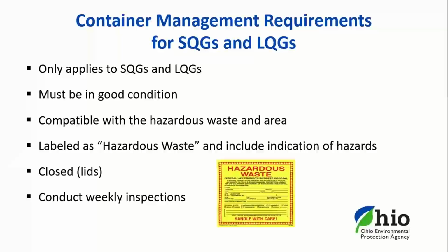The container management requirements only apply to SQGs and LQGs. The containers need to be in good condition, so no signs of dents, bulges, corrosion, or visible leaks. The containers need to be compatible with the waste that's being stored, and they need to be properly labeled with the words hazardous waste and an indication of the hazards. Lids need to be kept closed except for when you're adding or removing waste or temporarily venting the container, and the container areas need to be inspected weekly.